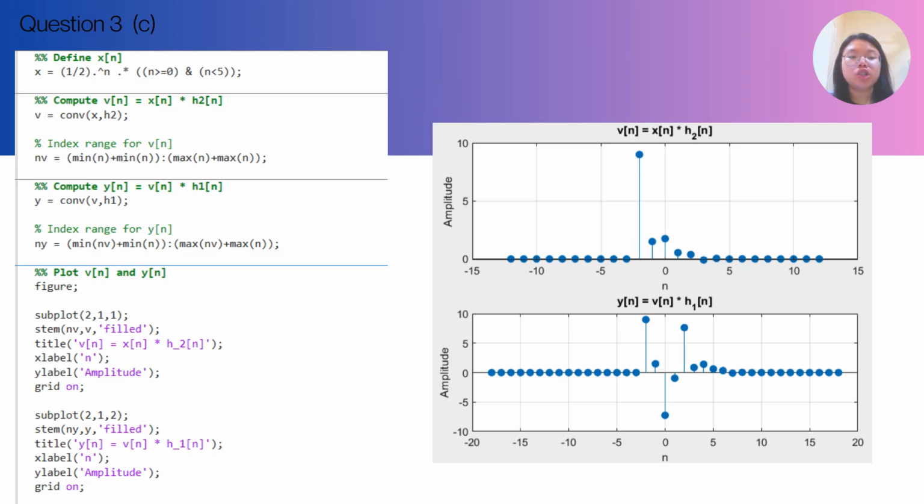In general, convolution is commutative, meaning A convolved with B equals B convolved with A. However, that's for signal convolution. Here we have two different systems in cascade. Since convolution is associative and commutative, the overall impulse response of the cascade should be the same regardless of order. That means h total equals h1 convolved with h2, which is the same as h2 convolved with h1. Therefore, theoretically both configurations should produce the same final output yn.